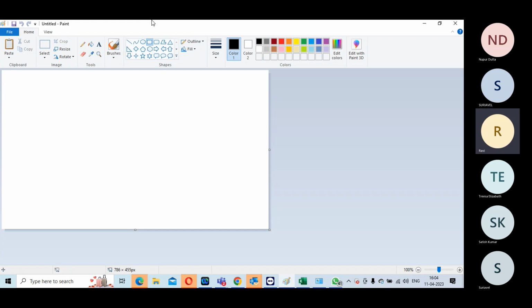So when you are doing clock tree, you have to analyze it while you are doing your clock tree in the worst slow corner, and you should also check for the fast corner, how your skew variation is big. Why? Because the skew can be because of net delay or because of cell delay.